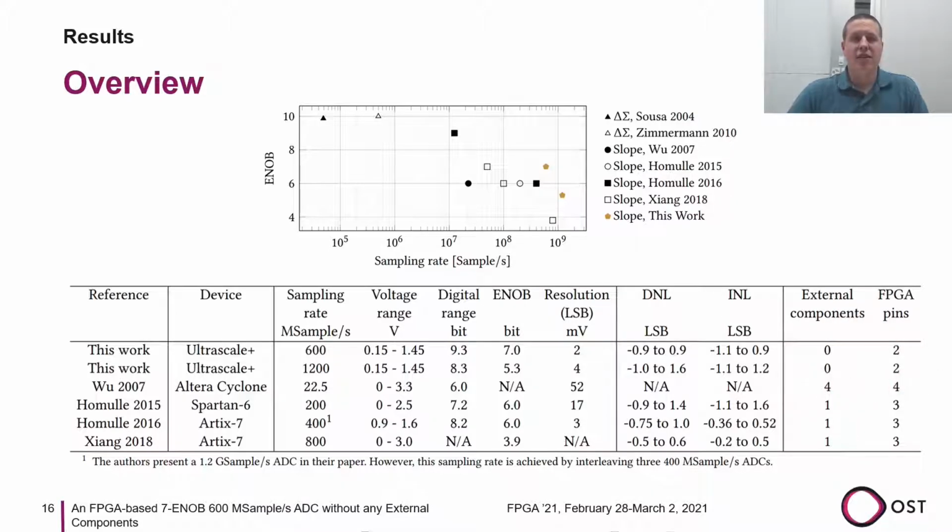As there are no external elements required, it is for example also possible to first use the LVDS interface as such, and then later the FPGA can be reconfigured to act as ADC on the same pins without the need for a hardware change.